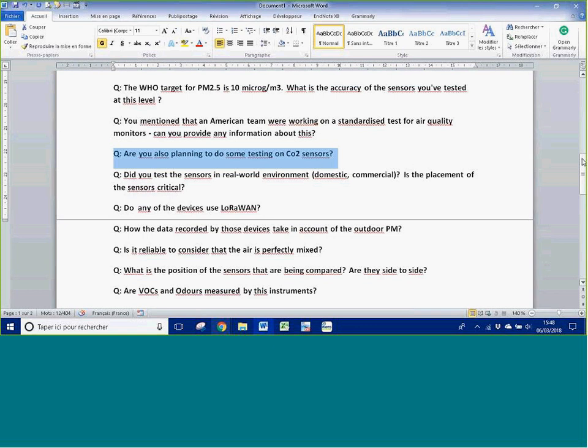But there are other people, I believe, still doing research in this area of can we make our CO2 sensors more reliable. Similarly, we'd have to do this with particle sensors also, right? If their output drifts with time or the calibrations change with time, like we found with CO2 sensors, they're going to need some sort of periodic recalibration. Our experience, at least in the US, in commercial buildings, is the periodic recalibration just doesn't happen very often, if at all, because it's not part of the building maintenance schedule.